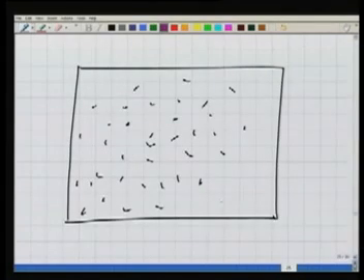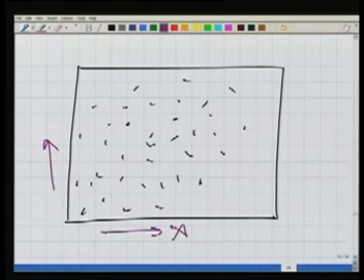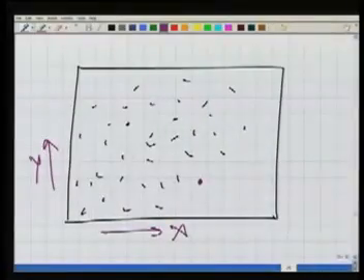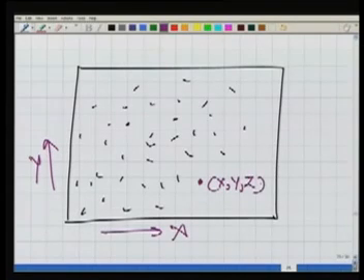So here in this map, we had already plotted x and y in planimetry, but at the same time now we also know for any point its x, y and z. With this information, is it possible that I can locate my contour?